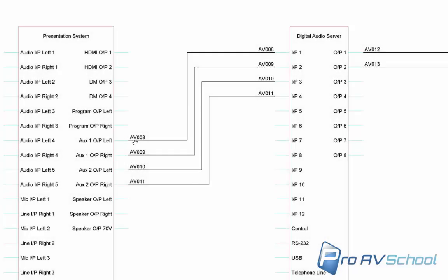So I'm basically working on a system here that has a DMPS 300. We're using aux1 out as room 1, aux2 out as room 2 into a Tesira and output to each room. So basically we're going to, in the inputs, mix these, and depending on whether it's combined or separated, we're going to combine or separate the volumes.